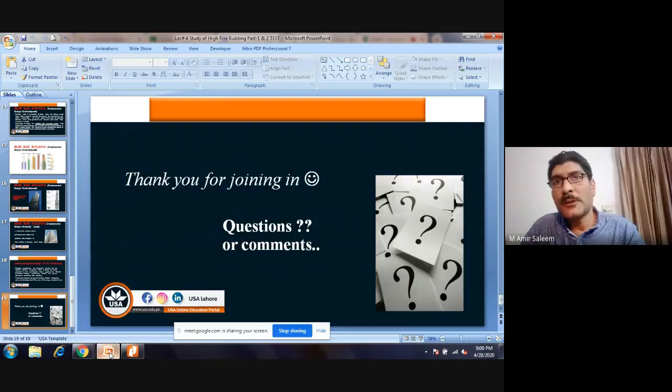Before concluding this lecture, one thing is very important for an architect. We must have clear knowledge of where we are going to design the building. If we are going to design a building in Lahore, we must understand their earthquake position and the zoning of the earthquake, the soil capacity, the availability of materials, the availability of skilled labor, and the sources.